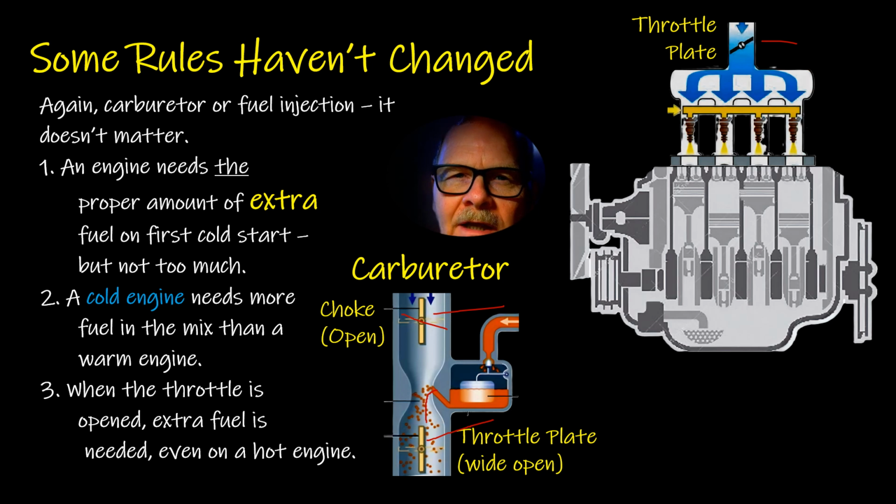Okay, so if you ever are able to watch this on a really fast scope that will measure those injector pulses, as you're applying the throttle, you'll see extra injector pulses inserted between the ones that are triggered by the crankshaft. It puts extra fuel in there that way. And so as that throttle is moving, you're going to get extra fuel just because it's trying to act like there's an accelerator pump. Remember, the engine still needs the same thing, whether it's fuel injected or mechanically done with the carburetor, and it actually does it electronically.